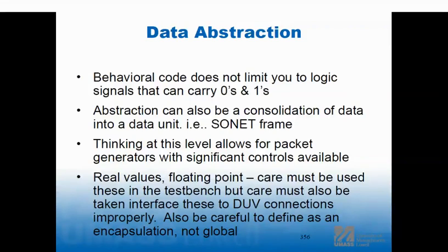And then I do that, and then I maybe have a filter on the other side that's in my test bench, right? So my bus functional model in the receiver has a filter in it that takes that noise out to see that I still have my fundamental signal. Or maybe I have a notch filter that takes the fundamental signal out to see the profile of noise to see if it's the same as the profile of noise there. Right, so this is a little less conventionally constrained random stimulus because I have to be a lot smarter about what the randomness is. Because you put random data into a signal processing system, you get random data out. Right? It's very difficult to find that.